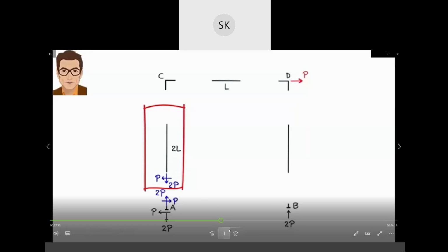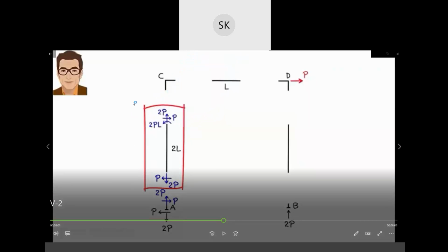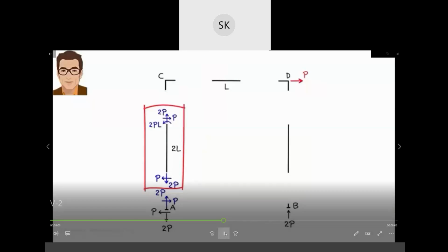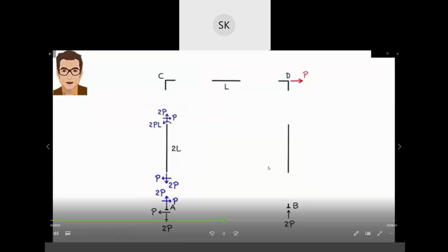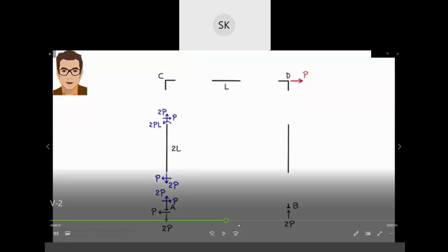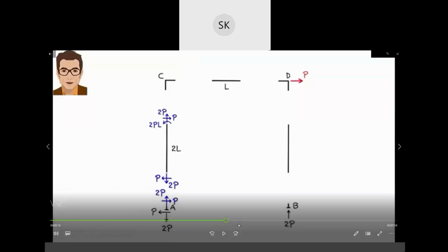Sum of the bending moments about, say, point A must be 0. So we get, they have separated the systems to find out the forces in those members. Now draw joint C and balance the forces at the joint. They have related the forces with the energy.